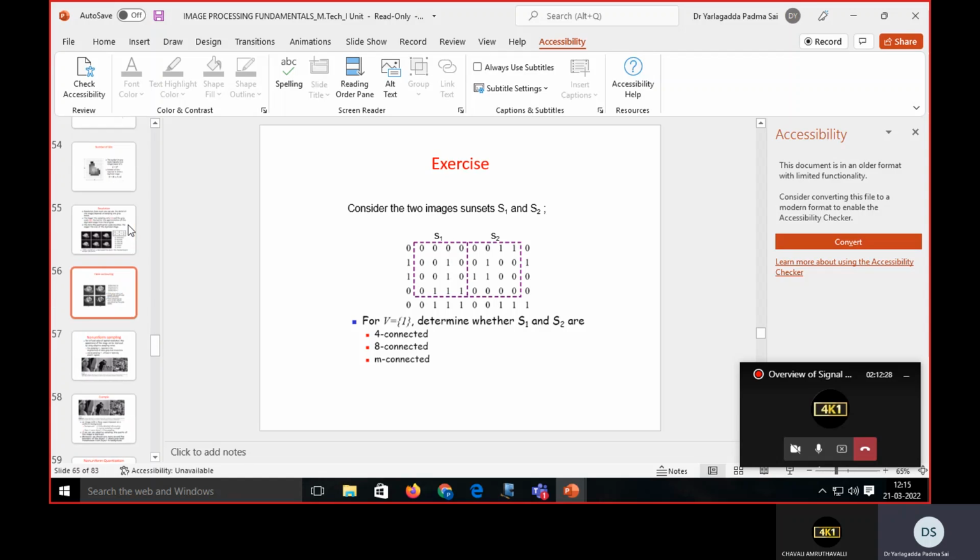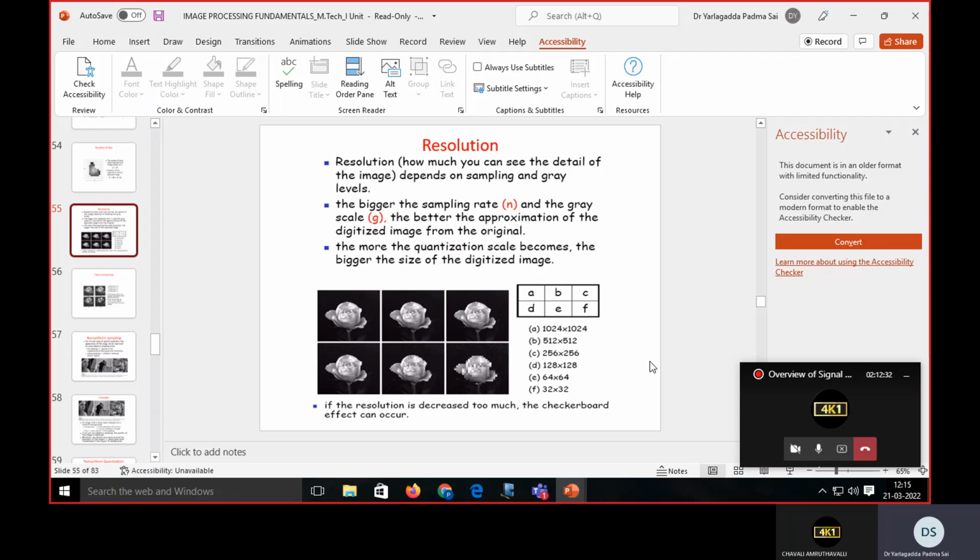You should be able to talk about it even though you are not aware of the processing, even though it is 2D convolution, everything is there. Once you are capturing an image, you have to do pre-processing. In pre-processing, among the Fourier transforms, for images mainly we are using the discrete cosine transform.